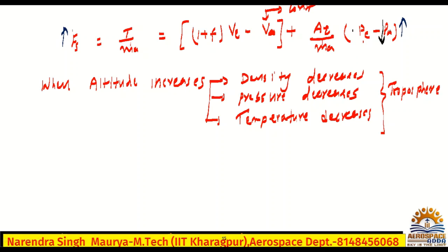All right. I hope you all understand this. Yes or no? Now a very generic formula from the nozzle. Suppose this is the nozzle, because whatever exhaust you have in a jet engine, you are getting thrust from the nozzle. So for the nozzle, if this is the exit velocity V, the temperature will be Te, or total temperature I will write T naught e. Yes or no? And we have the surrounding temperature, which is T infinity. What is the Ve value?